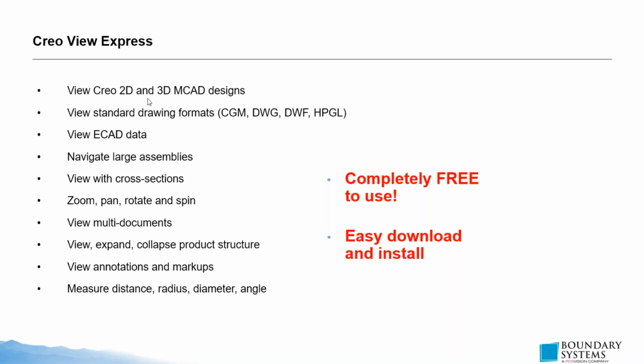We can choose to view different parts of large assemblies or hide other parts if we would like. For example, if we open a car file, so a big assembly file that has all the different parts of a car, we can choose to hide certain parts at once, such as the interior, the body, the engine, etc., to look at whatever part we would like to more specifically.